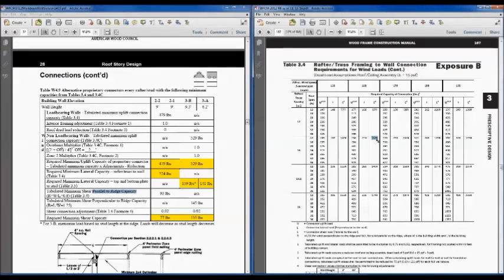This has a little bit more of a calculation you have to do. So depending on which way the wind you're looking at for this particular, it's 116 R. R down here is the length to width ratio. So in this particular case, our length to width ratio, or width to length, in this case is 0.8. So that adjusts that 116 times 0.8, adjusts that to 93 pounds.